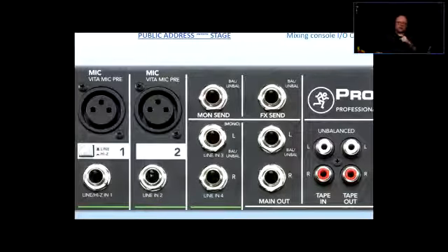Now, power is voltage times current, in an electrical signal, right? When it comes to displaying things on an oscilloscope, usually you won't be able to display the power of a signal, but you're going to be able to display voltage. So voltage is slightly different. When it comes to voltage, in order to double the voltage, you're going to raise not 3 decibels, but 6 decibels. You're going to have double the voltage. Or if you lower the voltage 6 decibels, you're going to cut the voltage in half. Right? So voltage doubles with 6 dB, power doubles with 3 dB.